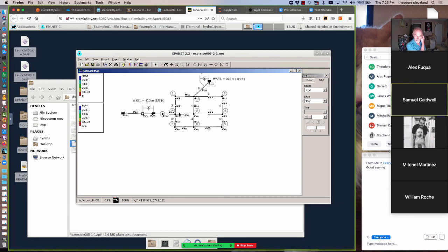You should create 2 nodes just for the pump, rather than do the lazy way, which would be to go straight from the reservoir to this node and then through the 900 feet of pipe or whatever it is to get into the system. The flow answers will be the same, but I feel that this is a superior way to conceptualize these problems.